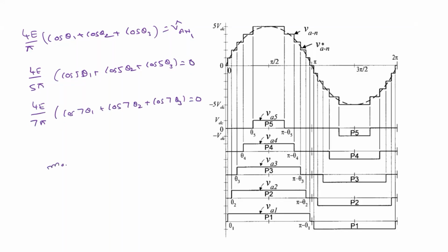So what is MA we defined, right? So we can equate this into MA, or straight away we can solve this one. If you solve this, you can get theta 1, theta 2 and theta 3. These are transcendental equations. We can use the Newton-Raphson method or any other iterative method. By using that, we can solve this. So you will get theta 1 as 57.110 degrees, theta 2 as 28.7 degrees, and theta 3 roughly 11.5 degrees.